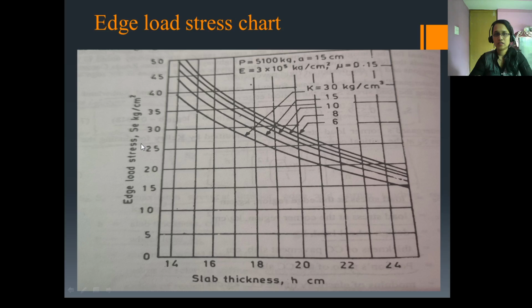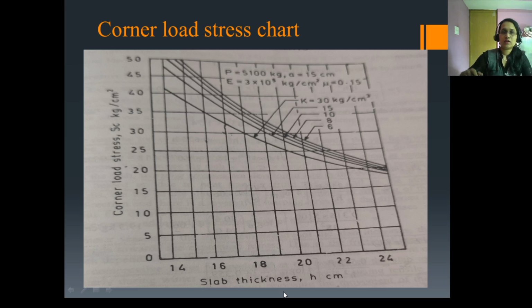So we can find the edge load stresses with the help of this chart here, corresponding to these K values and the slab thickness. Similarly, for corner load stress, we can find the corner load stress using the K values here and the slab thickness.